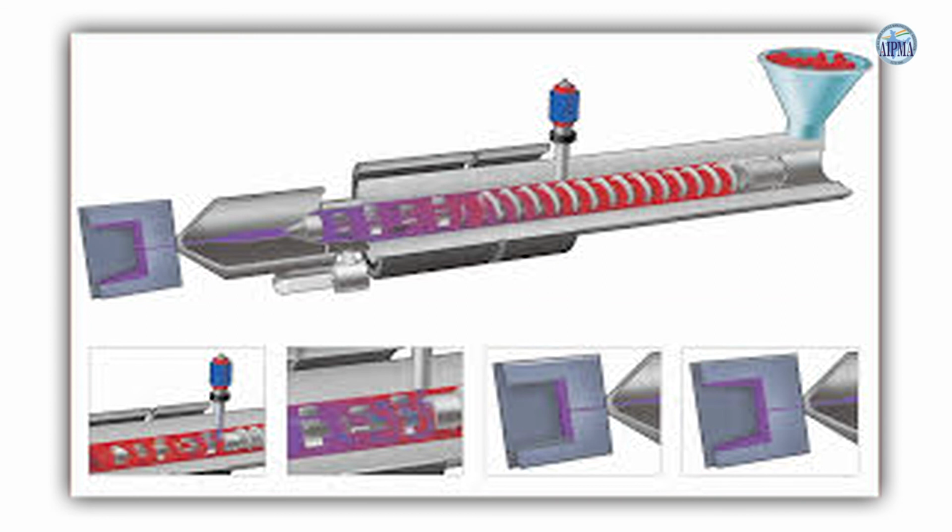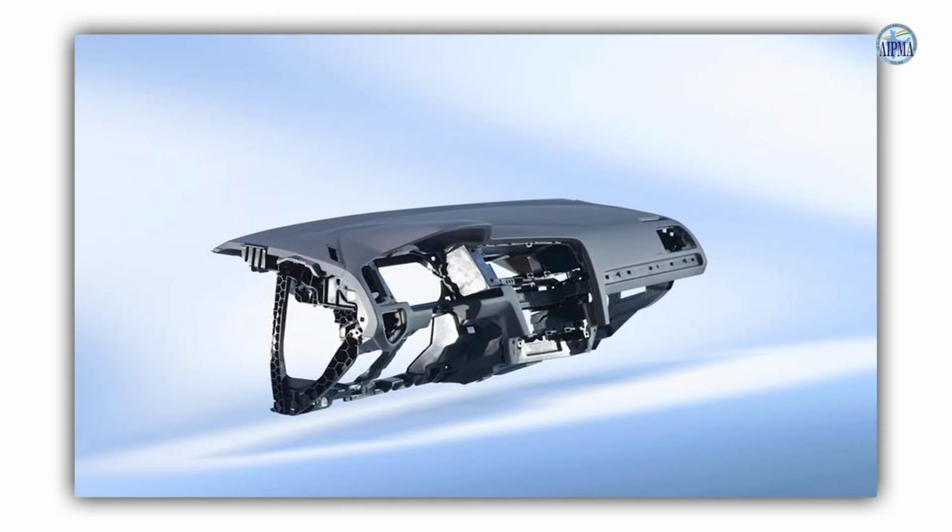Mucell offers many advantages over conventional injection technologies such as less shrinkage, less weight, low materials cost, and fewer sink marks. In addition, Mucell produced parts show less warping and closer tolerances, and in many cases also cool more quickly.